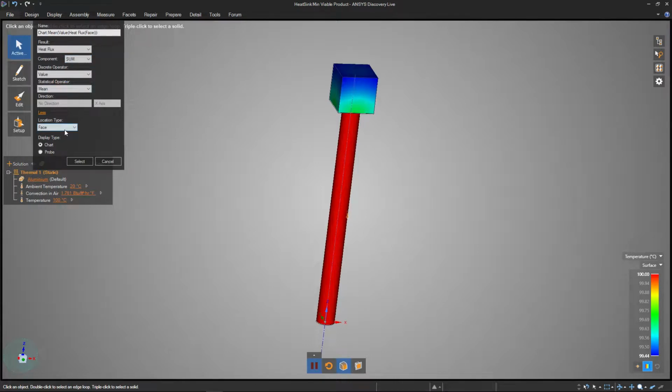The third and final thing we need to do here is the location type. In this option, we're going to drop it down and select body so that if we add new faces to the body, it will automatically include those. If we put a valley into the cube at the top there, the internal faces won't get included right away unless we select this option here, body.